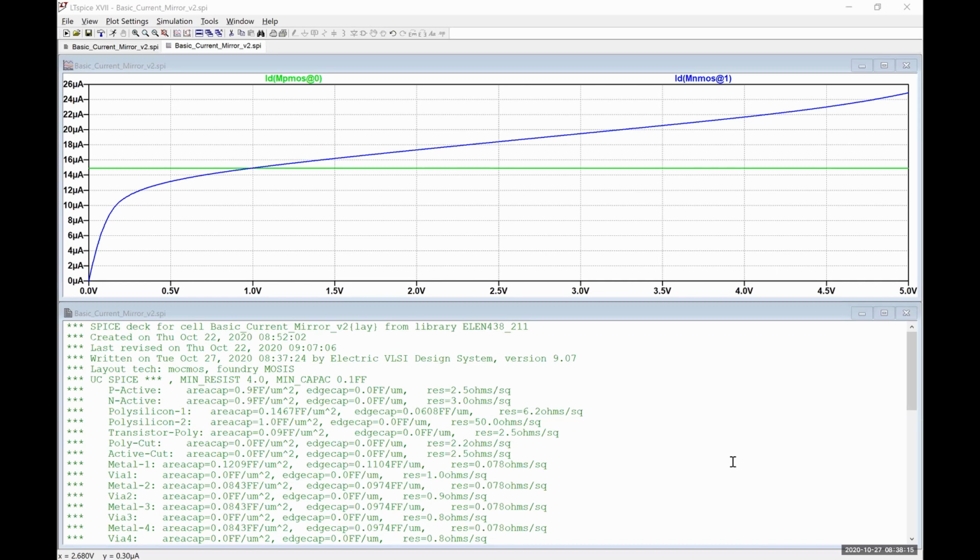And so I suggested that we change the width of the PMOS transistor. Did anybody actually go about doing that and figure out what we needed to get it down to get 20 microamps? I messed with it a little bit, but I think I might have done something wrong because for some reason it actually shot up. So I've definitely messed up something somewhere. Okay. Anybody else give it a whirl? All right. Well, nobody's volunteering anything, so let's take a couple of minutes and get that guy fixed before we jump into our other one.